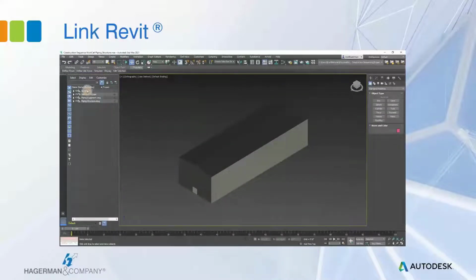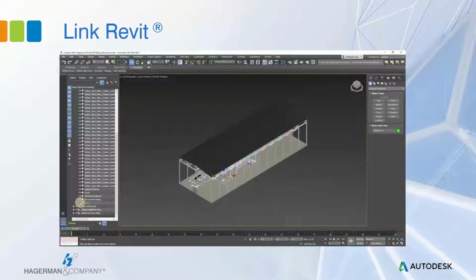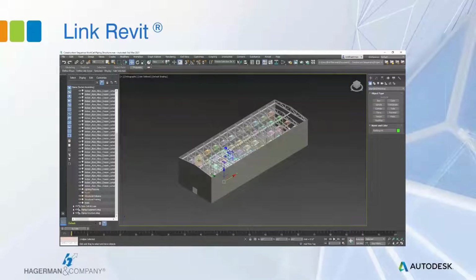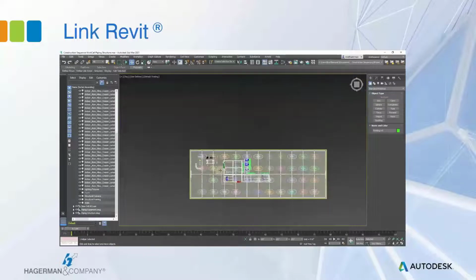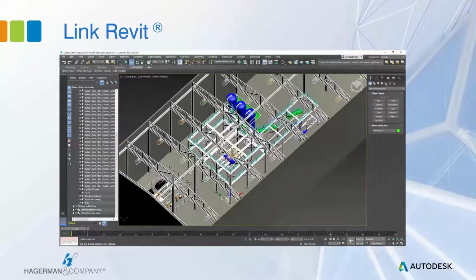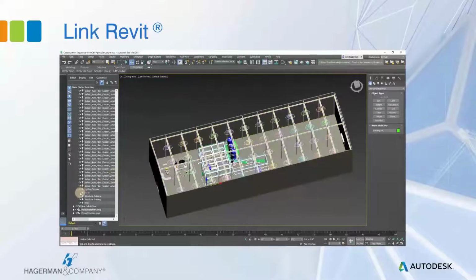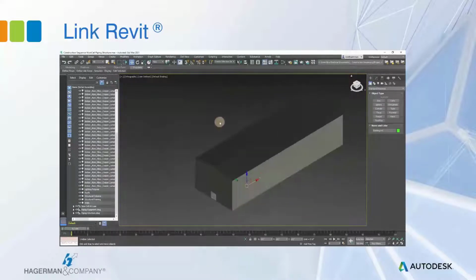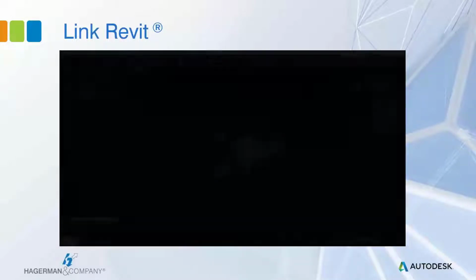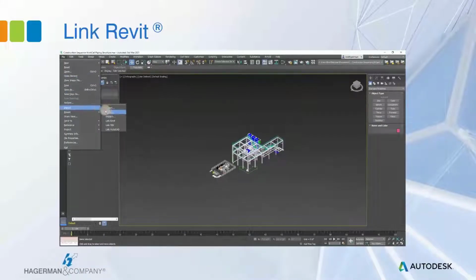And there you go. And that also landed right where it's supposed to. It's also grouped in the Scene Explorer like the others. So I have 4 wrapped up line items in the Scene Explorer in Max. I can control the visibility just like I would with layers in an AutoCAD file or with categories in Revit. So here I've just got the roof hidden temporarily to take a look inside, make sure everything is where I would want it. Once you have all your files in place, then we can turn our eyes onto the walkthroughs.